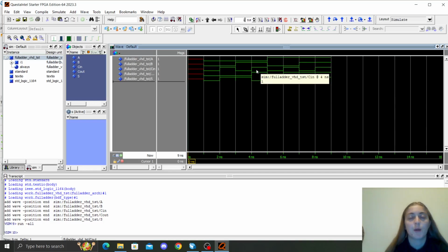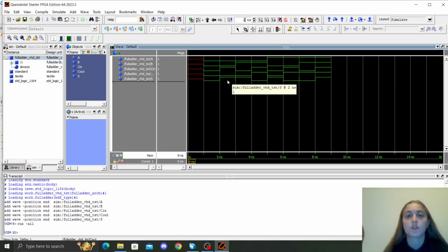or from schematic, and then this is correct because CN, if that is the only bit that is on or 1, then your Cout, or sorry, your sum is 1, your Cout is 0, and then if you have 2 that are on, which is this is B and CN, then Cout is 1. So this waveform is correct, so the logic is correct.